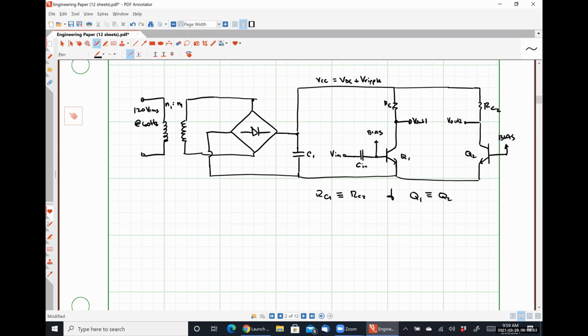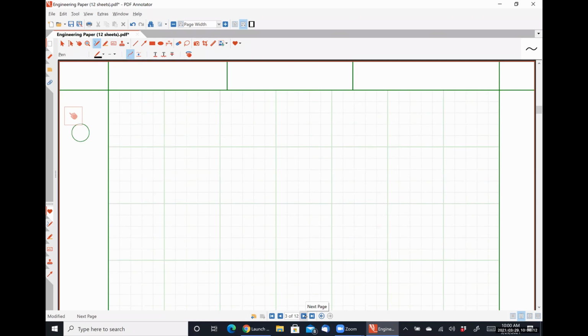And what we are going to observe is what's called common mode gain, meaning we are still going to be amplifying some small portion of our ripple signal, because we haven't made a further restriction, okay? So now let's talk about the BJT differential pair, which solves this.